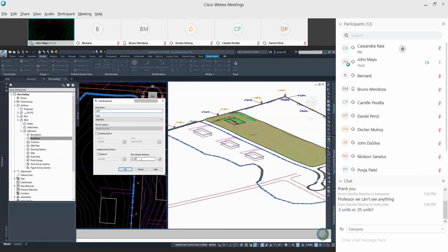And this is important to note when you have feature lines with curves, because the feature lines are really modeled in a tin as triangles, and it needs to break your curve up into little segments. This value should get smaller with smaller radii and larger with large radii. If I had a 1,000 foot radius, I might set this at 10 or 25 feet.